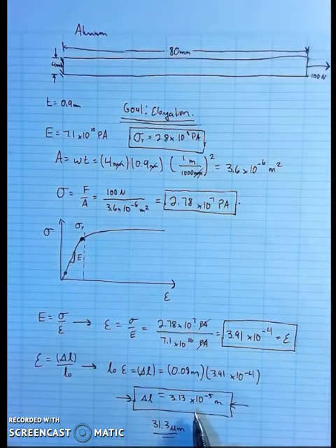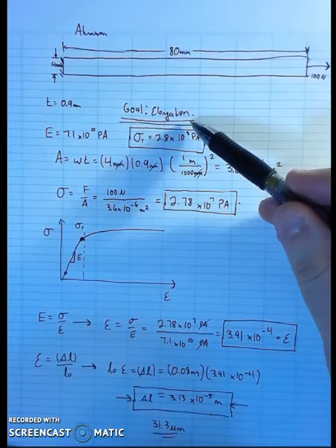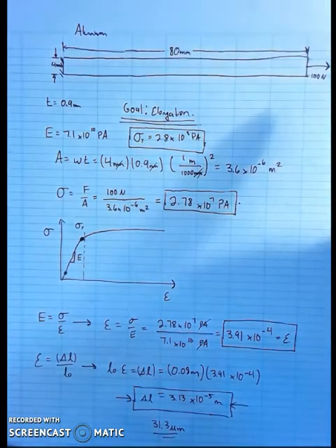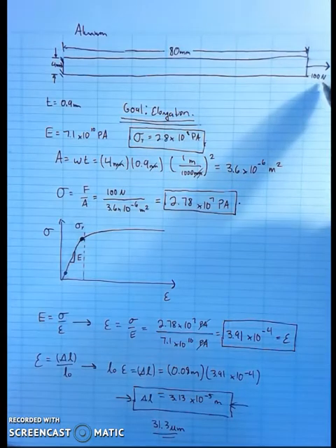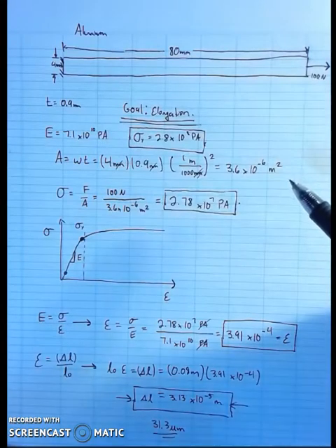But this is the number that we will be looking for in our ANSYS calculation, 3.13 times 10 to the negative 5th, which again is the elongation of this object, the PASCO sample coupon made out of aluminum, if I impose 100 newtons on it and clamp one side so that that side does not move.